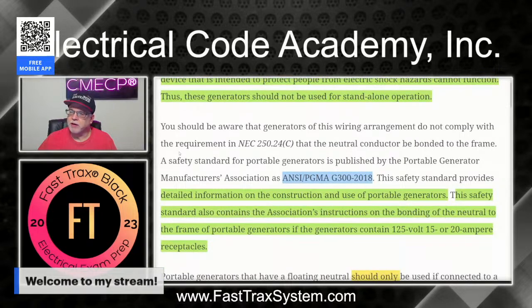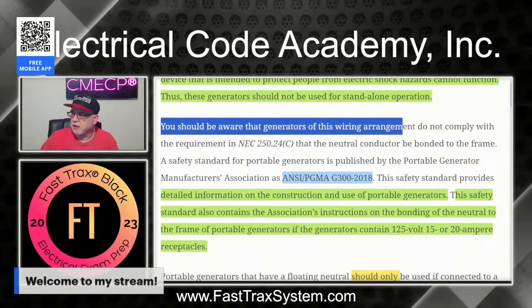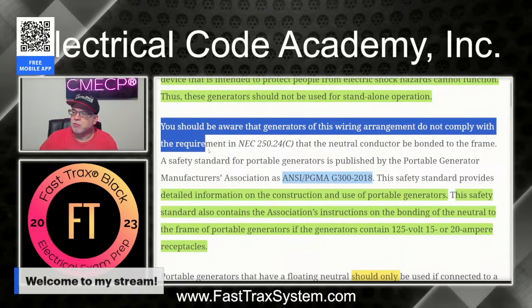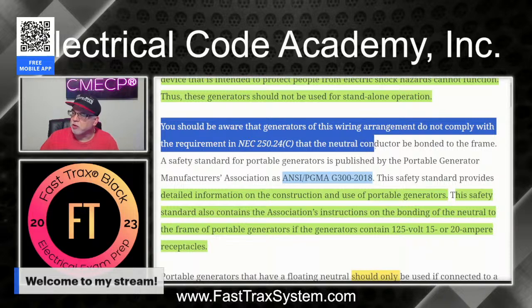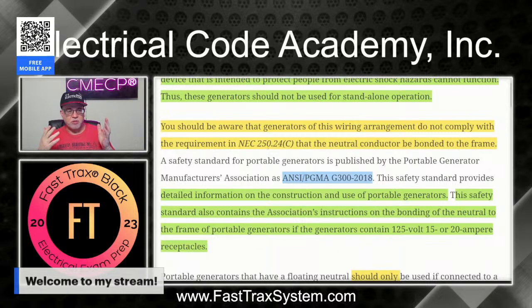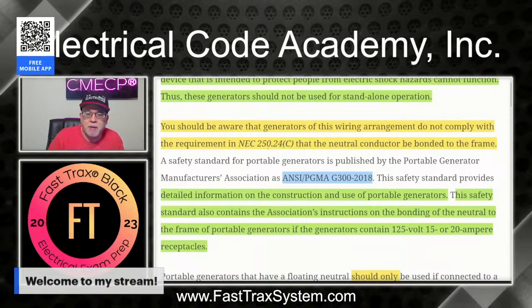Let's meet a little more here. It says, you should be aware that generators of this wiring arrangement, that is the one that's the floating neutral, by the way, do not comply with the requirements of 250.24(C) that the neutral conductor be bonded to the frame, okay? So again, first of all, trying to meet NEC rules, and this is going to become even more important